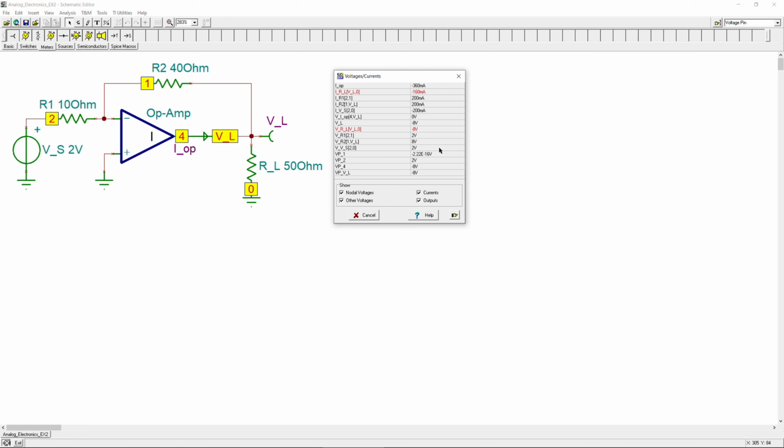I will also discuss a little bit more complex circuit using a T-network, which is also very helpful, where you want to have a large gain but still small values. Because if you want to have 100 times a gain or 10,000 times a gain or 1,000, and if this is 1K and you want 1,000 as a gain, then this must be 1 million. It could be a problem due to noise and other problems. That is, of course, a little bit advanced topic. And then we will see how we can still get that gain, but then relatively small values in total for the resistors.